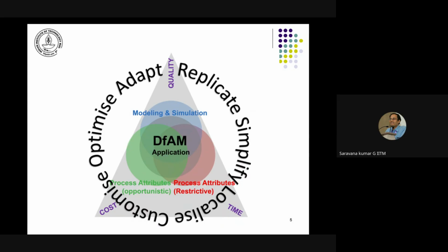So support structure is one thing, removal of support structure, and internal features are there. So then finishing may be an issue, even though we may have, say, some abrasive jet or other such processes which can be used to do some kind of finishing for internal channels. Again, that is an issue or a challenge that one has to consider at the time of design.